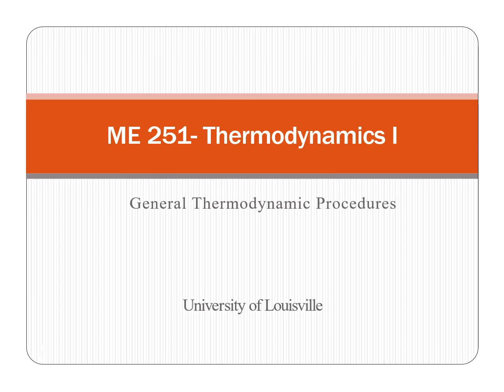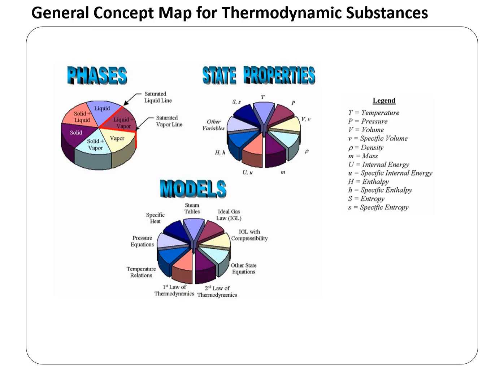So that's about the summary of the whole course. But the general procedure which you can follow in solving the problem is always highlight the keyword, try to see what substances are present. Is it steam? If it is steam, then it could be saturated mixture, it could be superheated vapor, it could be subcooled. So always try to look for what phases are present.